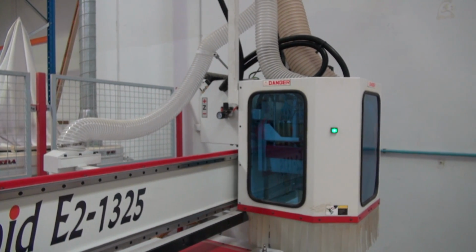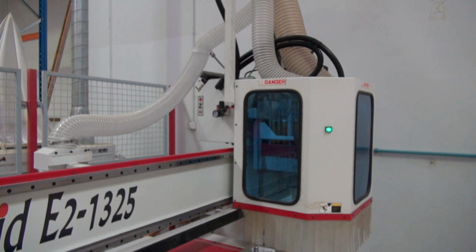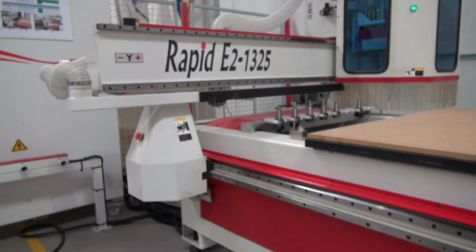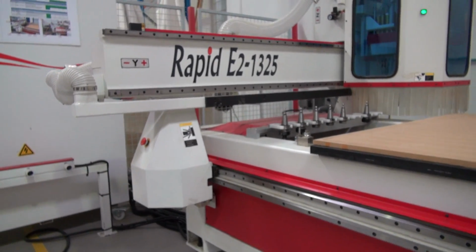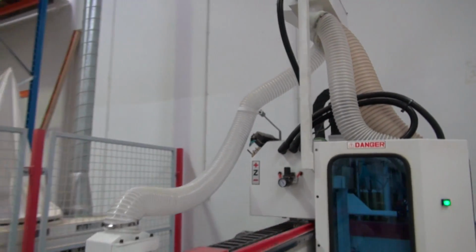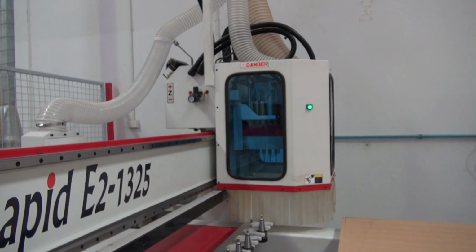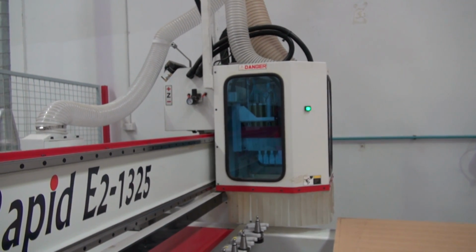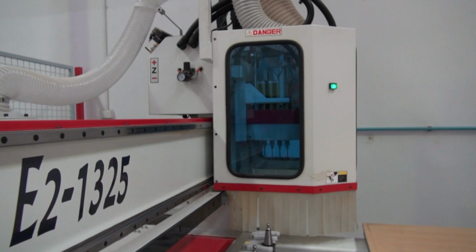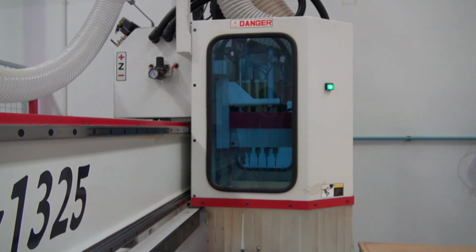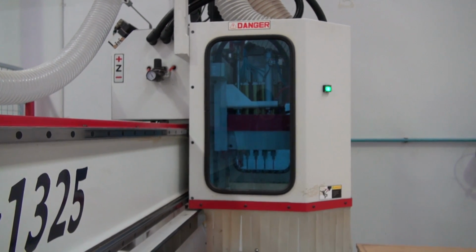It is crucial to understand how a CNC operates. The cutting or drilling head of this machine moves according to coordinates provided by the program and machine controller. All coordinates or instructions are given in reference to 3 axes: the X, Y, and Z axis. During the machine operations, the drilling head will travel across one axis or simultaneously across a number of axes, depending on the instructions sent to the machine.